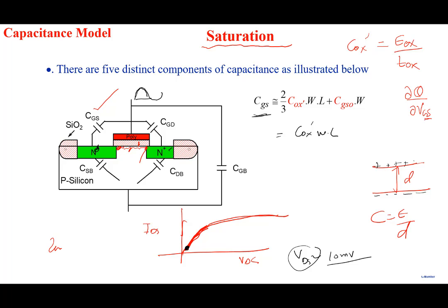Which means charge has to flow out. You need more positive charge at the gate, so charge has to flow out from here and from here also. There are two paths to it, and it will go to the gate. It will flow through both, since the terminals are equivalent when the drain voltage is small.